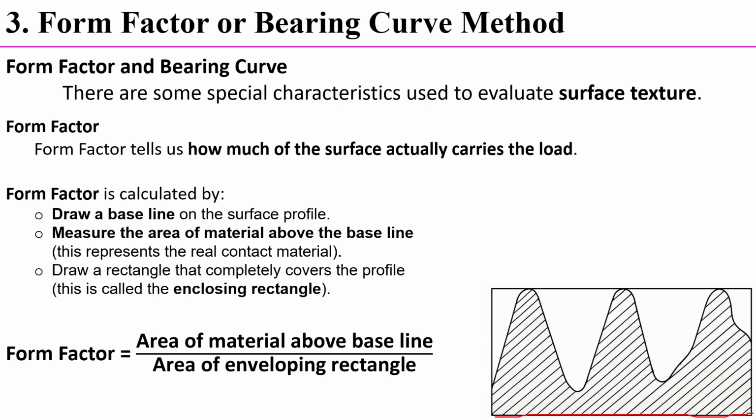Then I have to measure the area of the material above this baseline. Next I have to draw a rectangle with respect to this baseline, which completely covers the profile of the given sample length.